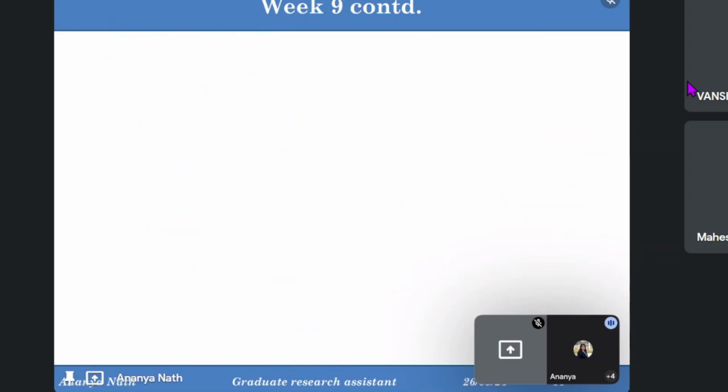So the next process is the two-phase process. Normally two-phase processes are used because you do not need to melt the particles. So what you can do is, you have the metal, melted aluminium, you just reduce the temperature of the melted aluminium, so it will have some starting of solidification, and at that time you add the particles, and both things will get deposited over the substrate, and it will be called two-phase processing.